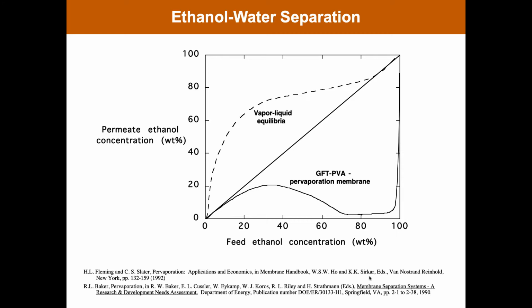Some of these plants are also set up then to make alcohol for fuel. And the way that works is that from the fermentation process, you get what they call beer, and it is fermented up until about 10 to 15% ethanol.